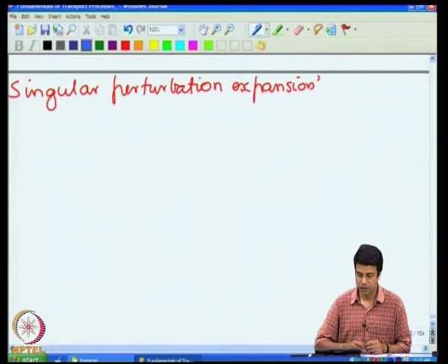And therefore, one has to postulate a layer of small thickness at the surface. Because the thickness is small, the gradients, the derivatives with respect to position, are large, in such a way that there is still a balance between convection and diffusion within this layer.